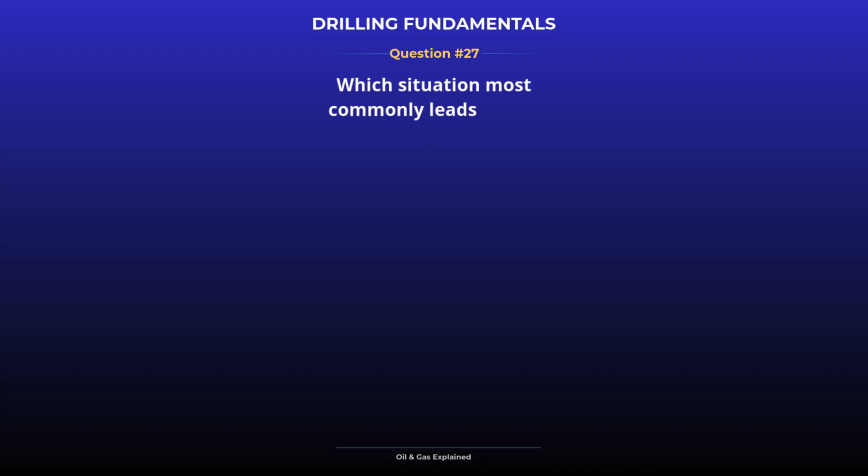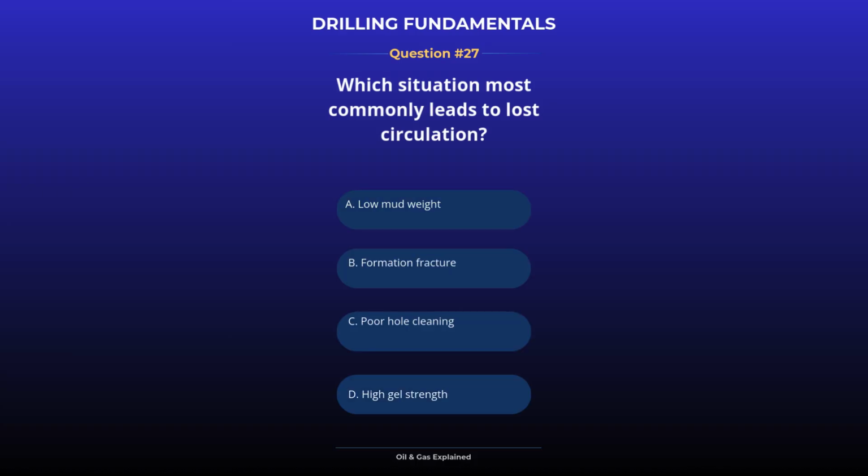Which situation most commonly leads to lost circulation? Lost circulation often occurs when formation fracture pressure is exceeded, allowing fluid to escape.